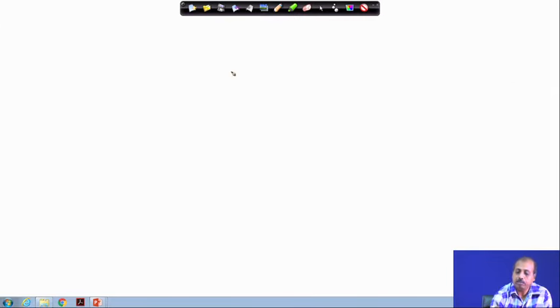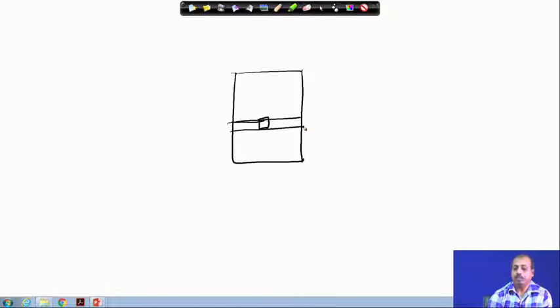It is never that we access a particular bit within a memory. It is not that we access a single bit separately. So this entire row is accessed by the processor. Now, if I have say m rows, then somehow the processor needs to tell which row it wants to access. To identify any row here, I will need log of m, I will need log of m number of bits to be specified.